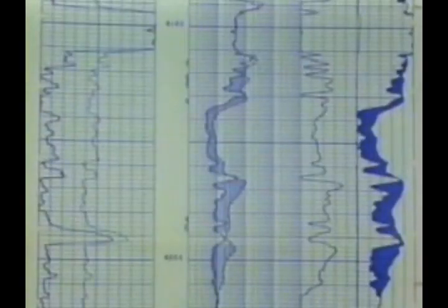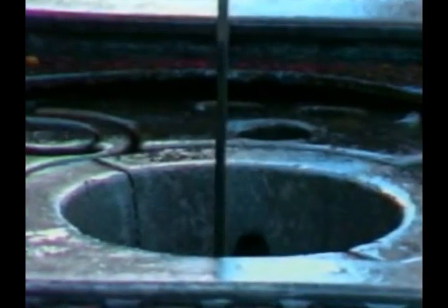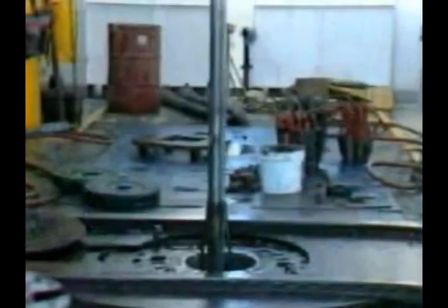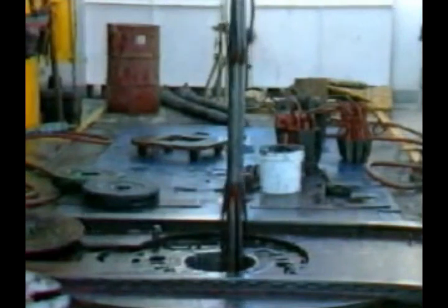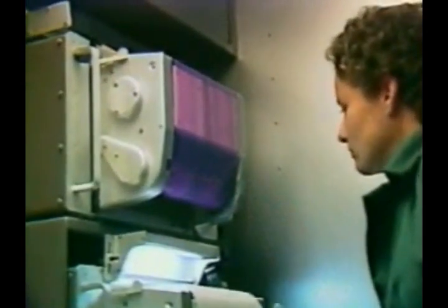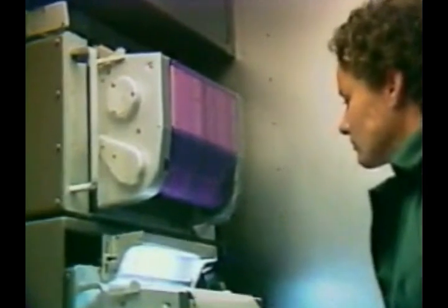Digital data are often evaluated and integrated at the well site through quick-look computer programs on board the logging unit. When logging of the selected interval is complete and the logging string is brought to surface, essential steps still remain before the logging phase is considered complete. The logging engineer must check to determine that the logging tools functioned normally and responded accurately to downhole conditions throughout the run. A quality control scan of the logs is usually done to verify this.